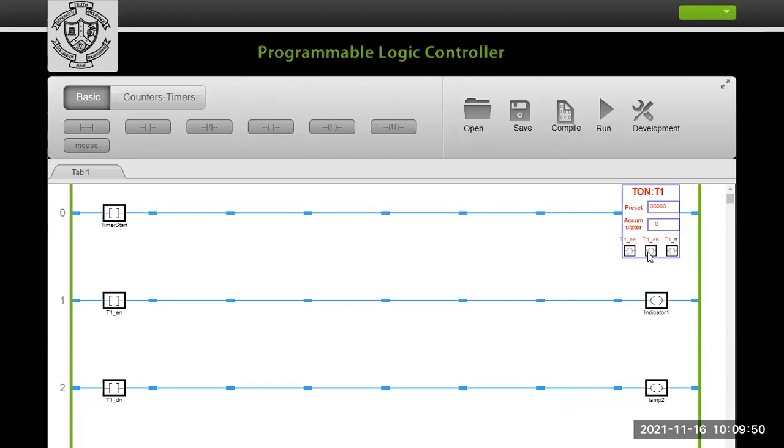First we start the star connection. After 5 seconds or 10 seconds, whenever it reaches the steady state, then we convert to the delta connection. Once the delta connection is transferred, we have no need of this timer, so at that moment the timer is disabled. Then if I directly connect this DN bit to the delta, the delta will also go off. But I want to run this motor throughout with the delta, so the delta should be latching. So I am going to the next program.